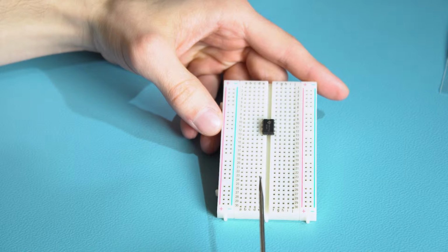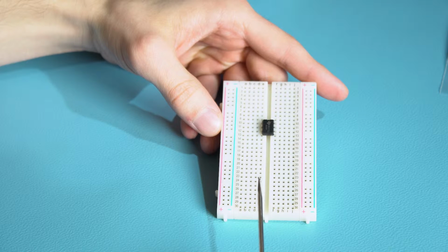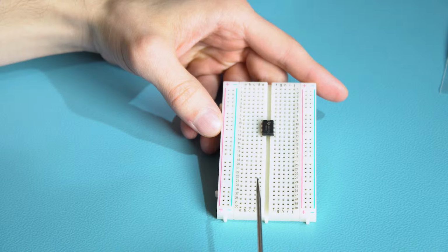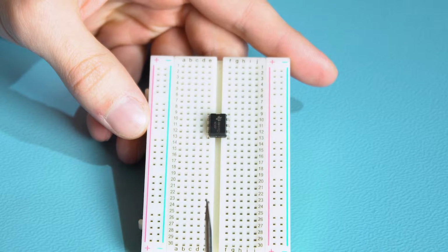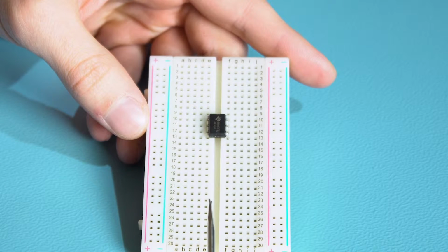The structure has 3 resistors with the same value. They form a voltage divider so that the comparators are supplied with voltage for comparison with inputs. For trigger, it's 1/3 of VCC voltage, and for threshold, it's 2/3 of VCC voltage.